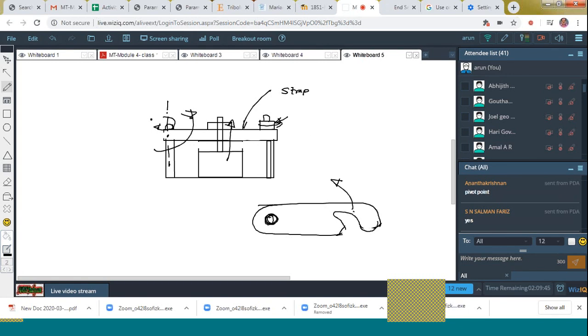Since it is rotating along a horizontal axis, it makes some obstruction for the upward movement of the workpiece. That is also one problem. To overcome that problem, the swing clamp is modified again. Up to this point, the strap clamp and the swing clamp are explained.